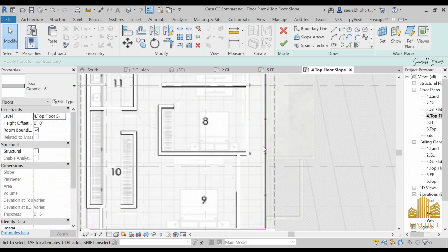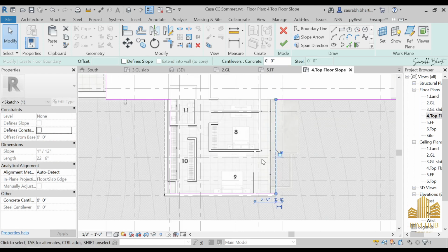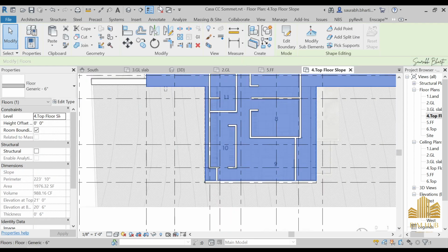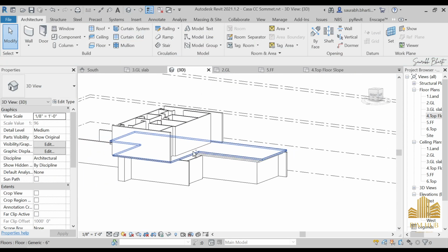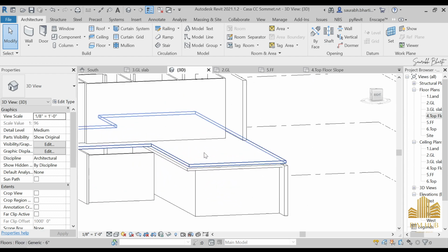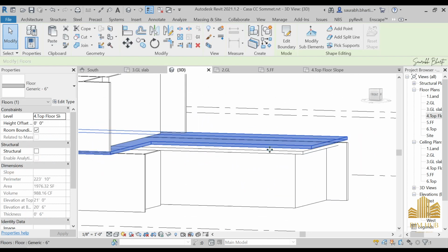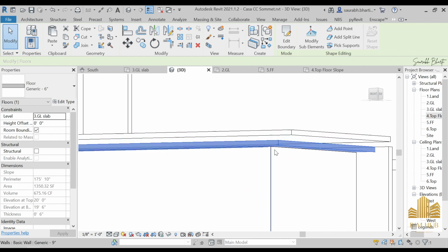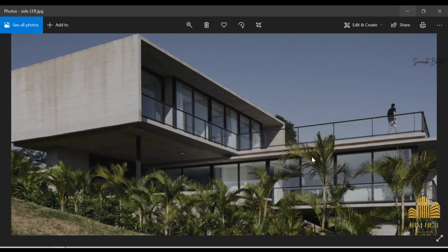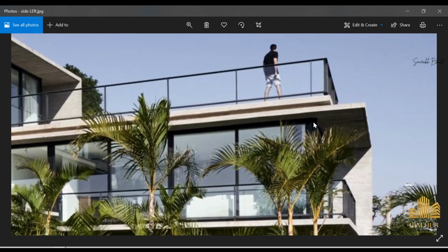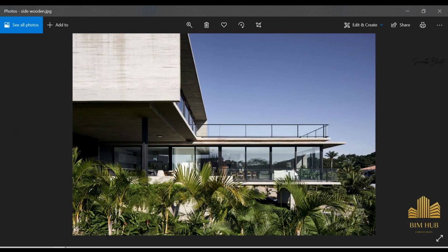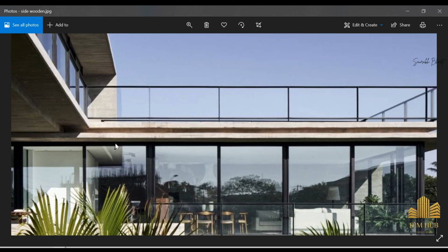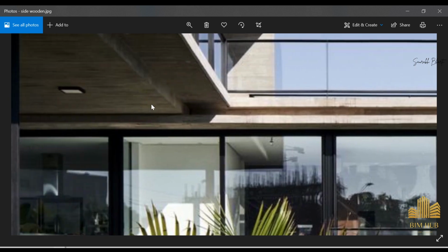So just select this floor and put it over here, and I think we need to select this one and put it till here and press OK and go to 3D view. And now as you can see, we have made a double floor over here. Is there any gap left in between? Yes, so in the gap we are going to make something in the middle, and we will make that with the help of sweep. Okay, can we do that with the help of sweep? Yes, we can do that.